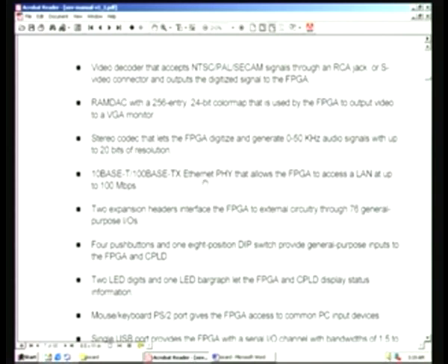and we have already seen you have an Ethernet chip for connecting it to a LAN, and up to 100 Mbps link is possible with this board, and you also have some expansion headers which we will be using for some of the applications that we are going to consider, and 2 expansion headers are available right on the board, and they are all basically connected to the FPGA IO pins, and total number of such IOs are 76, putting together both the expansion headers,